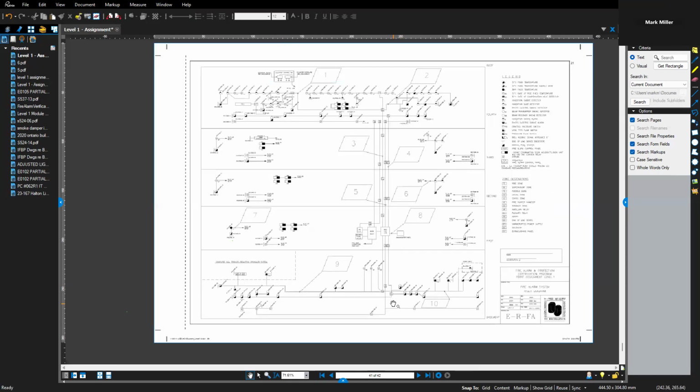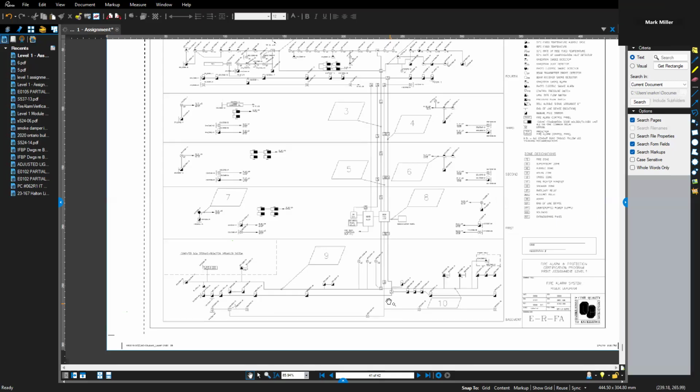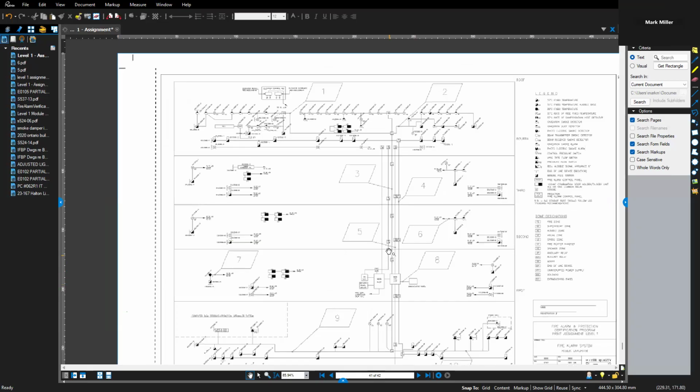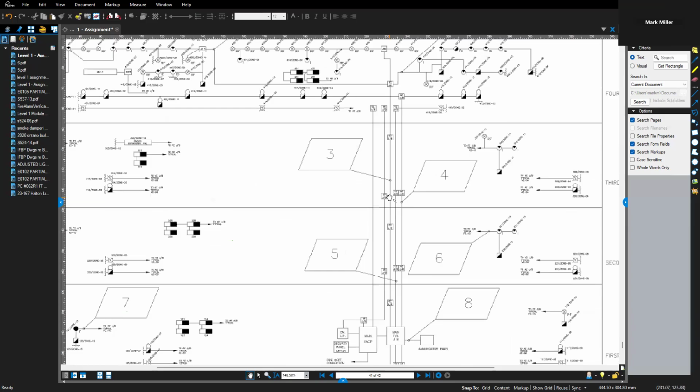So there's my main fire alarm control panel right down here on the first floor. I've got a riser pipe going up and then going over and up and into here. On our riser pipes, we've got a separate conduit for each wiring type. Our fire zones, our audible zones, and our visual zones are all in different pipes. Our ancillary relays are in a different pipe.